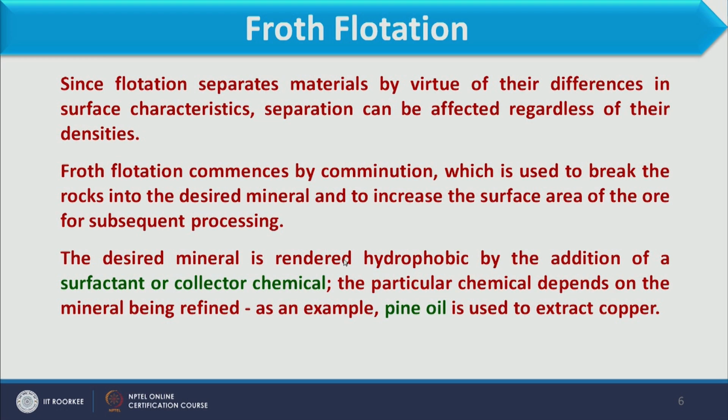The desired material is rendered hydrophobic by the addition of a surfactant or collector chemical. The particular chemical depends on the mineral being refined. As an example, pine oil is used to extract copper. So, here you see some surfactants we are using for changing the surface characteristics of the compound, and this surfactant will depend on the different compound.